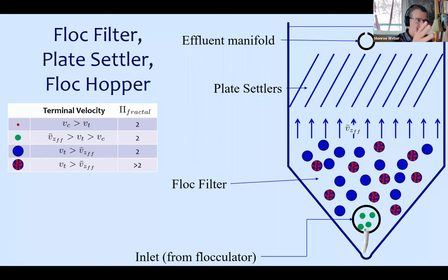So Ravi, you got to see a fluidized bed. The water is going up through the sand so fast that the sand ends up being fluidized, it moves around. And if you were to jump into that sand filter, please don't, you would sink right into that fluidized bed because it's no longer settled, there's no structure there, it's all a fluid, even though there's sand, which is not a fluid, but it acts like a fluid.